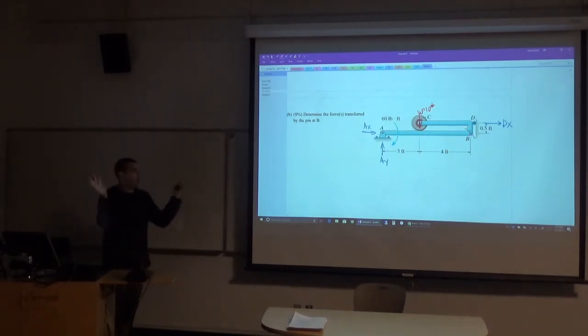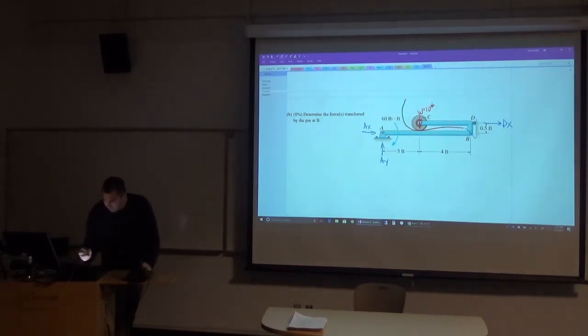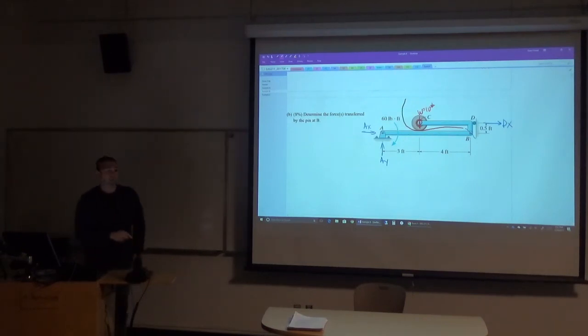Okay, all right. So where am I going to make my section cut? I can't go up. I can't go down. Yeah. What if I go horizontal here and right through there? Can I do that? What direction? I mean, this interface right here, a roller sitting on top of a flat surface, what direction is that force between them going? Or how many unknowns do I have being transferred on that surface?